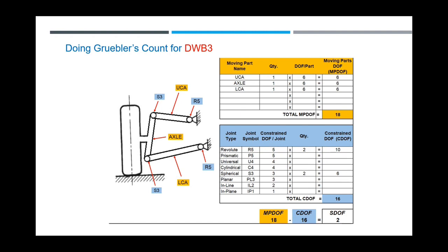And one thing that's nice about this mechanism is that you can handle torques better in this direction because it's spanned between the two discs here. Whereas the other one, the torque is taken up just by the lower arm alone, whereas the top one is following the direction, right? So those are two differences.